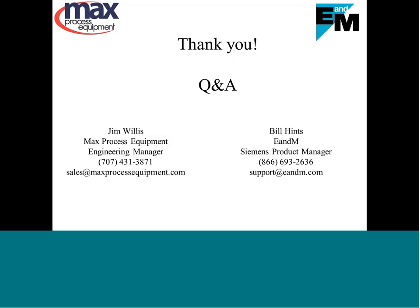Yeah. This is Jim. I just want to point out, I think you were part of the implementation years ago. We use pulse width modulation to open and close solenoids that take hot glycol heater material, working fluid, out of our heaters and put them into our recirculating lines.